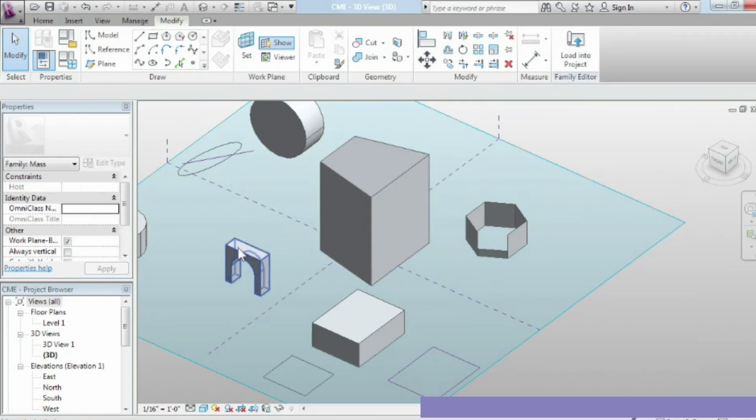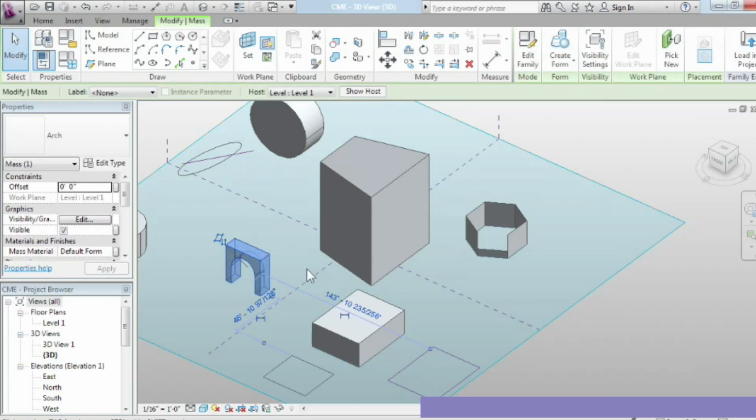Okay, now I come over here to this form and I highlight it, and it highlights a little differently. I didn't press the tab key, and yet it's highlighting the entire object. This one here, when I click on it, what we see is it's actually an object. This is a nested massing family that's just brought right into this project. So just like we can bring in any family into any project or other family, we can do the same thing here in the massing environment.